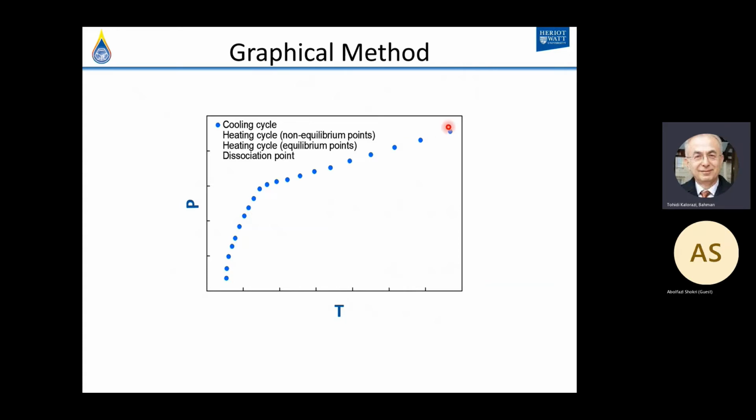So you have some gas component here. As the temperature drops, the volume is reduced, and we can totally predict this. And then here you see a sudden decrease in the pressure, and that is a result of hydrate formation. So here is the point that hydrate has formed.